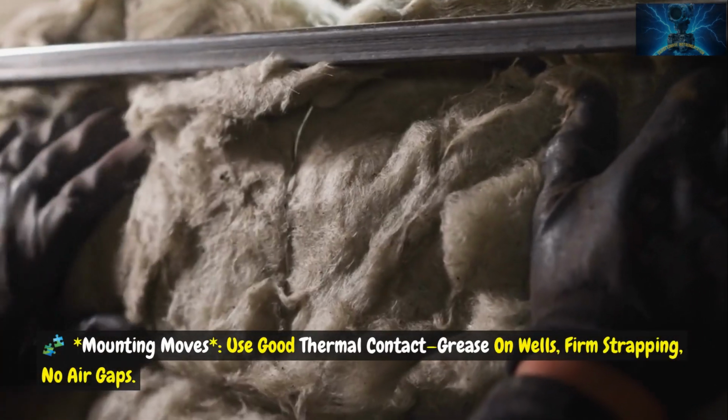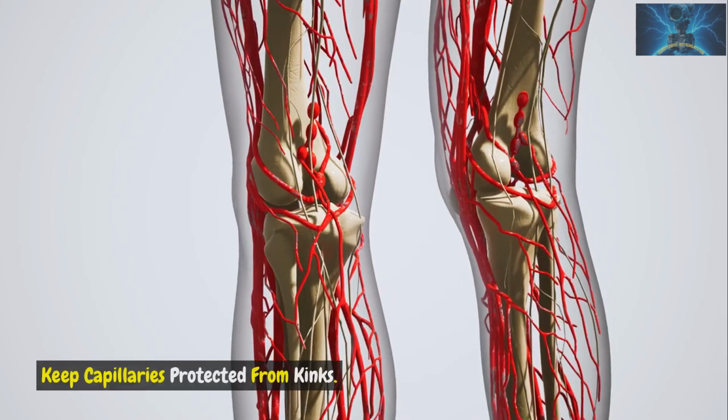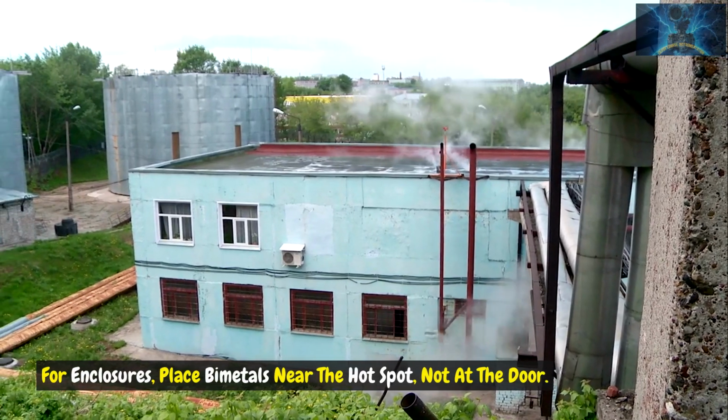Mounting moves. Use good thermal contact: grease on wells, firm strapping, no air gaps. Keep capillaries protected from kinks. For enclosures, place bimetals near the hot spot, not at the door.